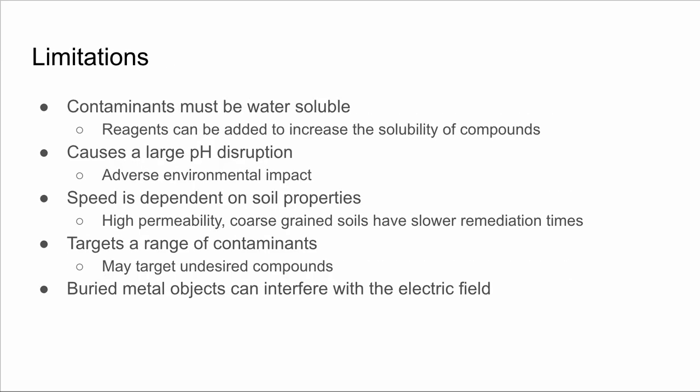All right, so a couple of limitations. The contaminants must be water soluble. If the contaminants aren't able to dissolve into the water, then there's no transport mechanism for them. So that's probably the biggest limitation on this type of remediation. Luckily, if you do have components that aren't water soluble, you can typically add reagents or surfactants to the water that will actually encourage the dissolution of those compounds into water. So you can get around that first limitation a little bit, just depending on what the type of contaminant is.